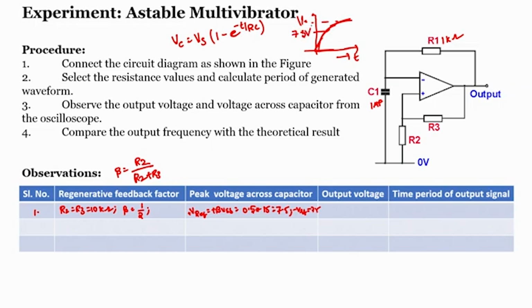We are not allowing the capacitor to charge more than 7.5 volts, because when the input voltage of the capacitor is greater than 7.5, the input connected to the RC filter is going to minus VCC, right. Because of that the maximum voltage is 7.5. So, I want to know the time taken for the capacitor to reach from 0 to 7.5 volts, right.